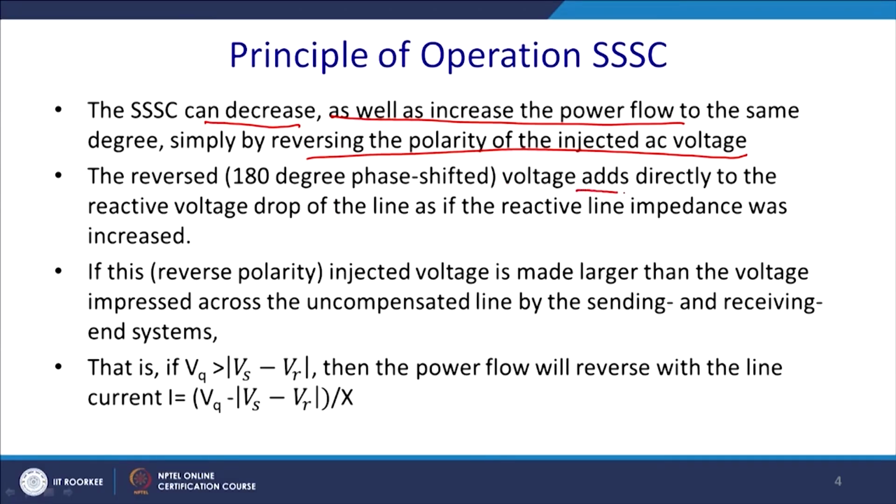Plus VQ increases the power capability, and you can reduce the capability of the line by injecting minus VQ. The reversed or 180 degree phase shifted voltage adds directly to the reactive voltage drop of the line as if the reactive line impedance is increased. So, the power transmitting capability will decrease.